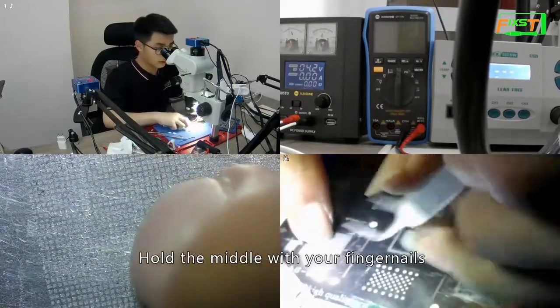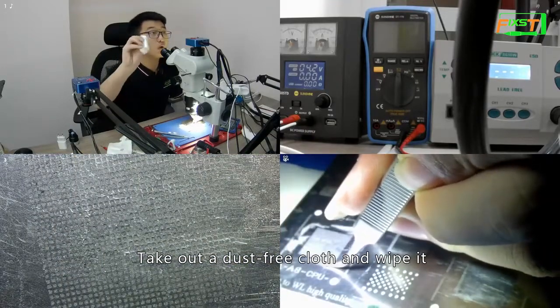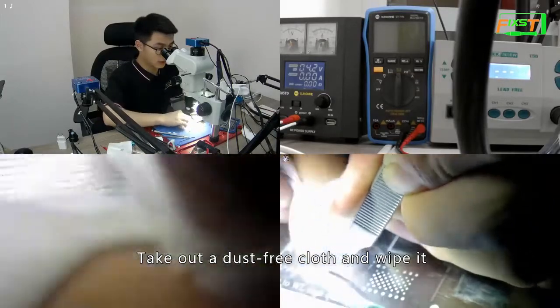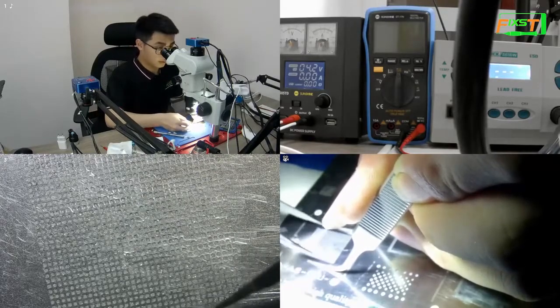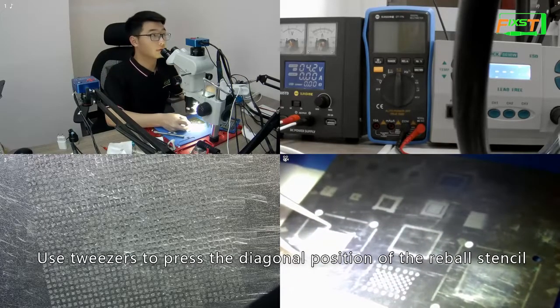Hold the middle with your fingernails. Take out the dust-free cloth and wipe it. Use tweezers to press the diagonal position of the reball stencil.